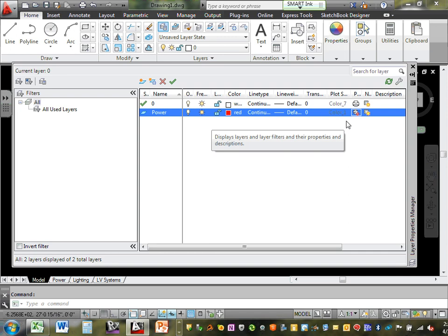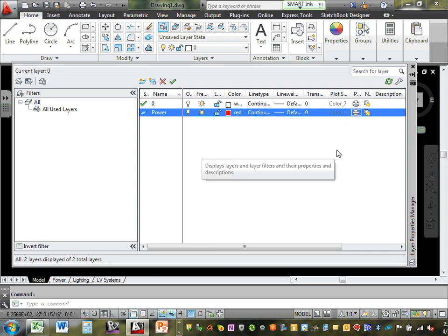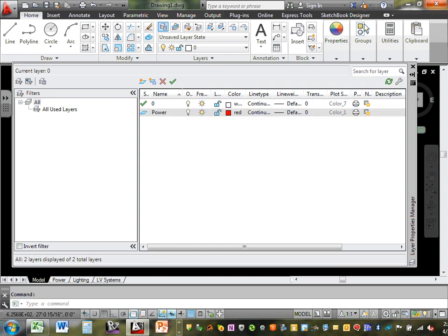So click on it right now, guys. You see that little red circle? This is telling the CAD that if you put anything on this layer, it will not print. So if you're printing things and something is visible but not printing, where would you go check? Check the layers, right there. That's a lot of mistakes students make, and in the work. So make sure it's unclicked. Or if certain things that you don't want to print are printing, they're on the wrong layer.